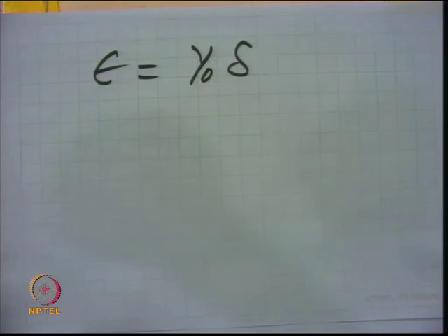So, one can define this epsilon based on this, and epsilon is also defined as y A0 times delta, where y A0 is the mole fraction of the limiting component. In this case it is pure cumene suppose fed, so it is 1. If it is mixed with some inert, because I told you inert may affect the rate, if you add 50% inert, suppose nitrogen along with cumene, then y A0 is 0.5. If you add 75% inert, then y A0 is 0.25.